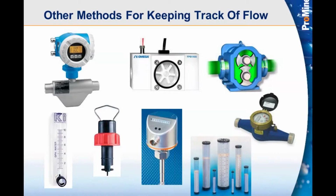Just below that, a water meter. That's just totalizing. It's not really giving you an instantaneous flow rate typically. Calibration columns, we're all familiar with those. That's how we're calculating a flow rate out of the pump. But we usually have to do a drawdown and then do a calculation to be able to determine what the flow rate actually is. If that flow rate changes, that calibration column is not indicating that to us unless we set that back up and have to do that calibration.